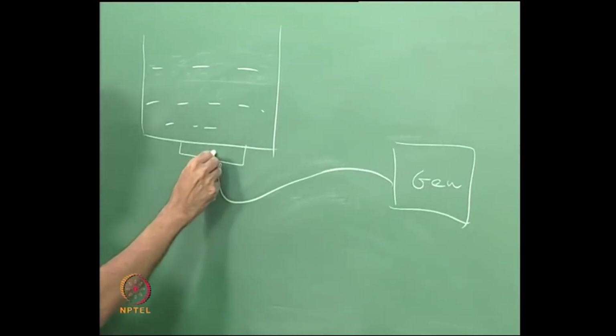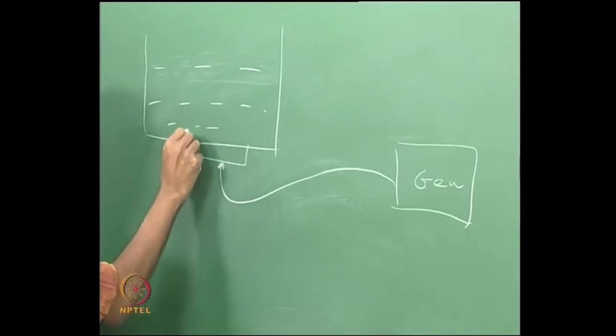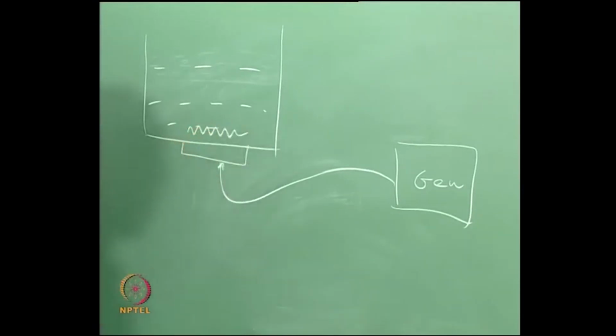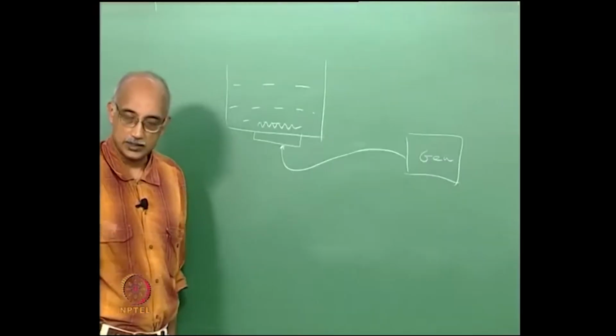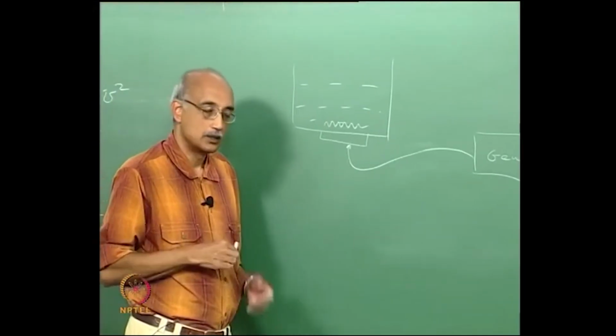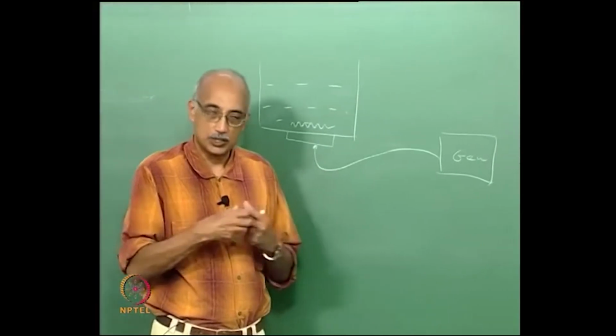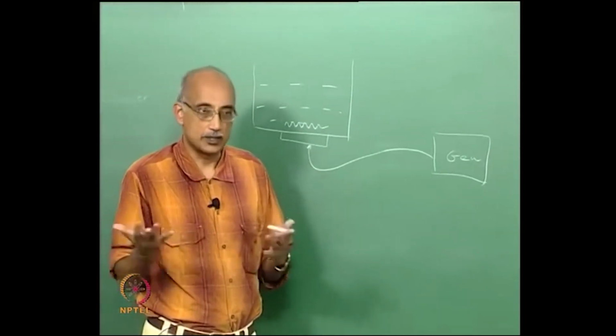Essentially, this transducer takes this energy input and converts it into an oscillating pressure field that is set up within the liquid. Now as the liquid oscillates, essentially you have a pressure excursion. The liquid keeps going through alternating phases of compression and expansion or rarefaction.